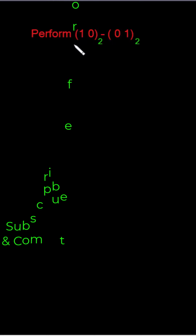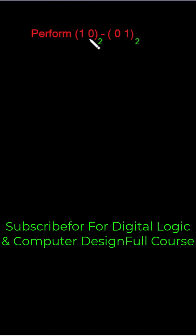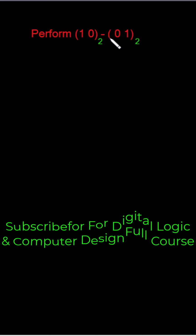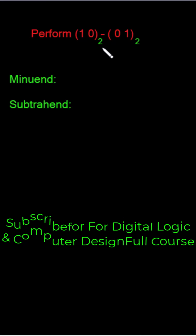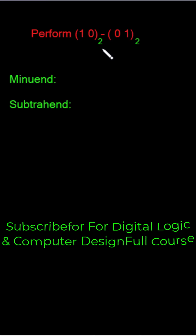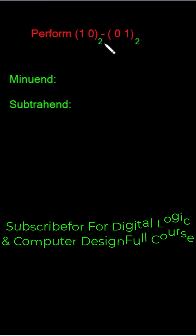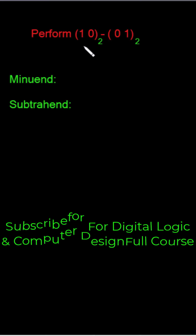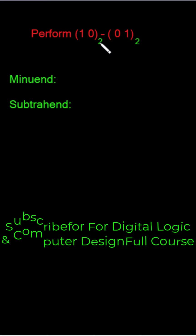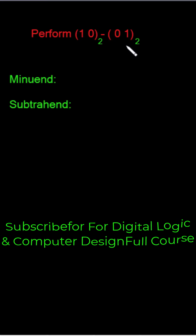In this question, we have been asked to perform binary subtraction, that is 10 minus 01. In binary subtraction, borrowing 1 from the next column will be equal to 2 in our active column. Why? Because this is base 2. Considering this one is the Minuend, the number we are subtracting from, and this will be the Subtrahend, the number we are subtracting.